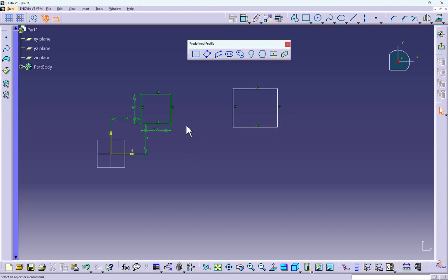So what difference does this make? If you move this, you can see it cannot move because it is defined completely. Once something is defined completely, it becomes fixed in its position and in its sizes. But here this component can move anywhere, it can displace from its actual position because its sizes are not defined. Once we define these sizes also, that also becomes green.